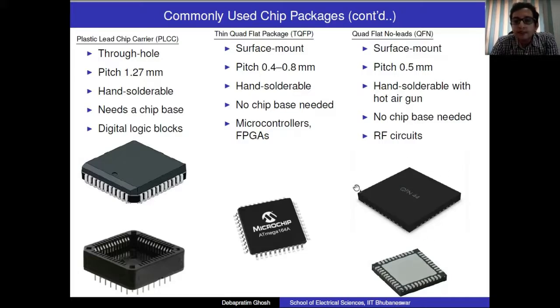The reason why they do this is because most QFN packages, whose top and bottom view you can see, have very little additional metal outside the package body, because these kinds of chips are used for high frequency applications. So to keep the parasitic components, parasitic inductance, capacitance, etc. at a bare minimum, the manufacturers prefer not to give any kind of leads.